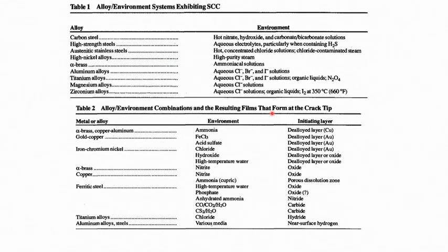Whenever there is leaching of the passive film formed on the surface, it acts as a zone where there is microgalvanic attack, and stress concentration is very high. So, it undergoes dissolution at a much faster rate. The environment is one where there is breaching of the typical passive film.